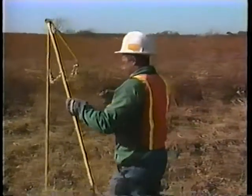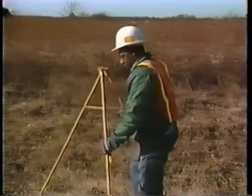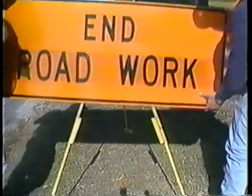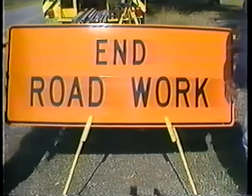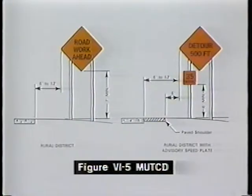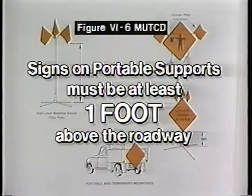Lightweight, yielding, or breakaway supports should be used for all sign installations. Sign installations should be reviewed to avoid any possible glare from vehicle headlights. The minimum height requirements for signs attached to posts is shown. Signs on portable supports are required to be at least 1 foot above the roadway.